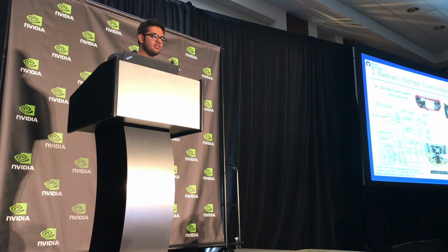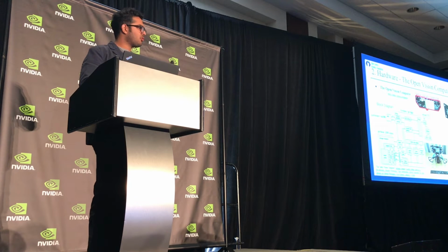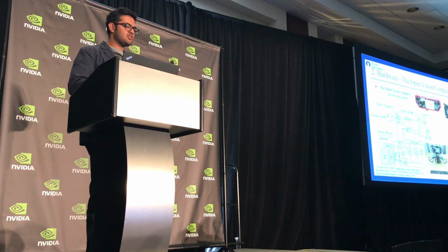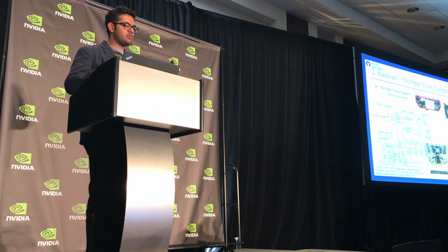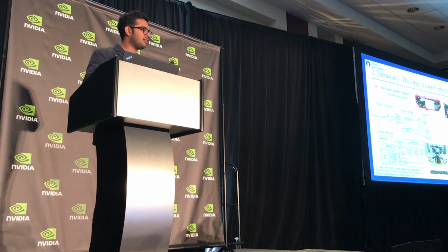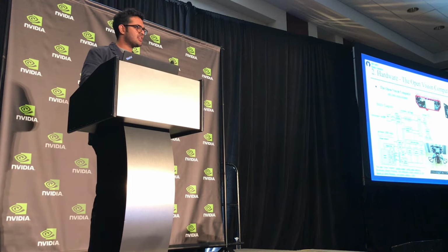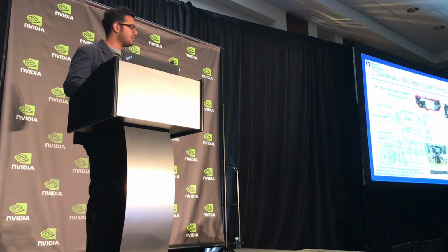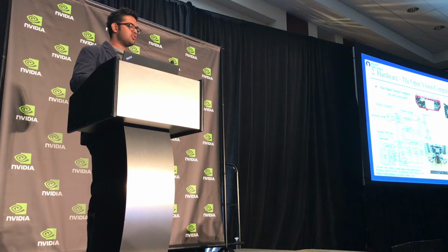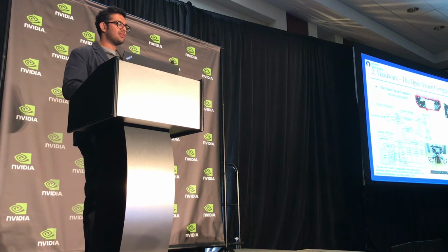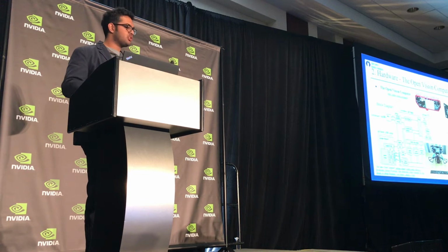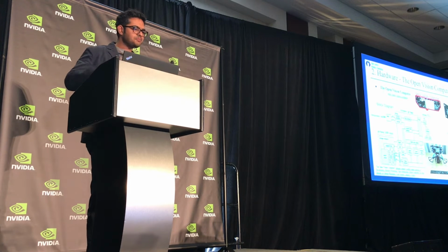So this is what in red was the prototype version of the Open Vision computer, and on the right is the current revision where it's at. So we have a TX2 that sits on this compute plate, which is connected to a sensor plate on the front. And these things can be swapped out if you don't want a stereo baseline, if you just want a single RGB camera, you can just switch out that front sensor plate, and you should be able to run our entire software stack on it and add your own. If you've been working with TX2 software, it would just be compatible.